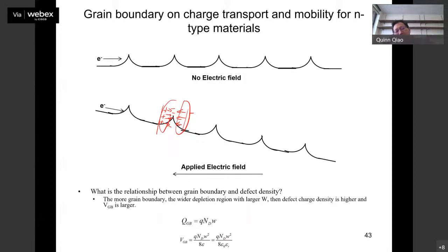This type of notch we are getting when we are moving in the structure from top to bottom, perpendicular to the PN junction. And if we are moving across the PN junction, then generally we are not finding this type of notch in the high electric field region, the depletion region.